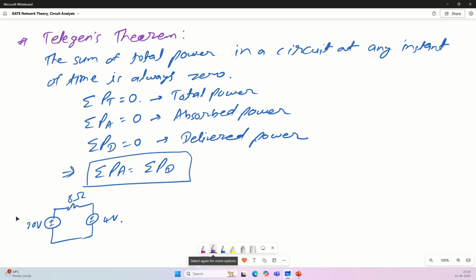So I will give you a trick about solving a circuit question. Whenever I am drawing a question circuit, that will be of one color, and if I am going to make some changes, you can make the same changes in your circuit, and you don't have to redraw the circuit. Okay, so that will be a solution circuit. So can you quickly tell me what will be the current flowing through this? So you know already 20 minus 4, that is 16, and 16 by 8, that is 2.